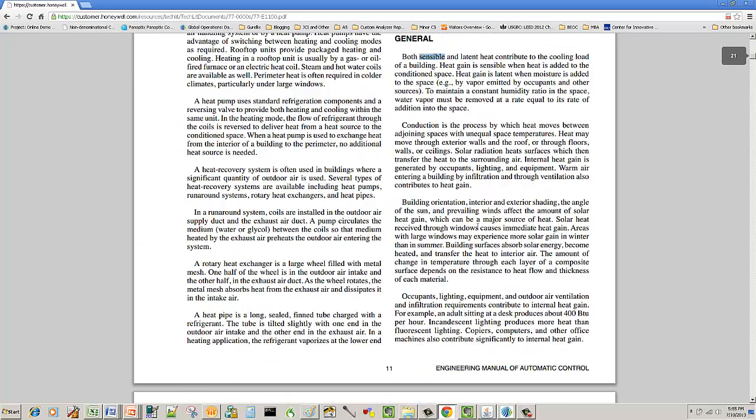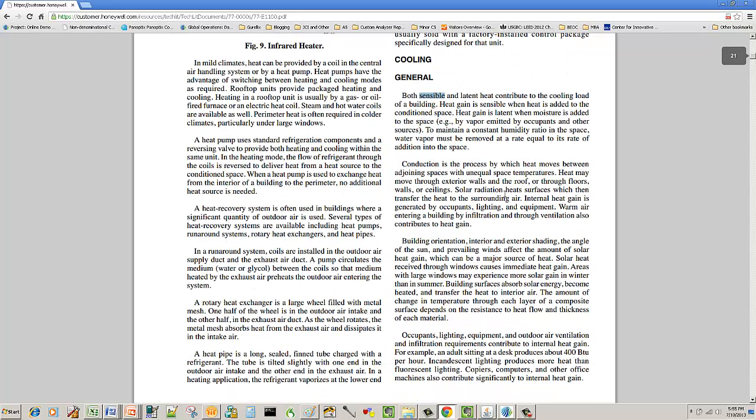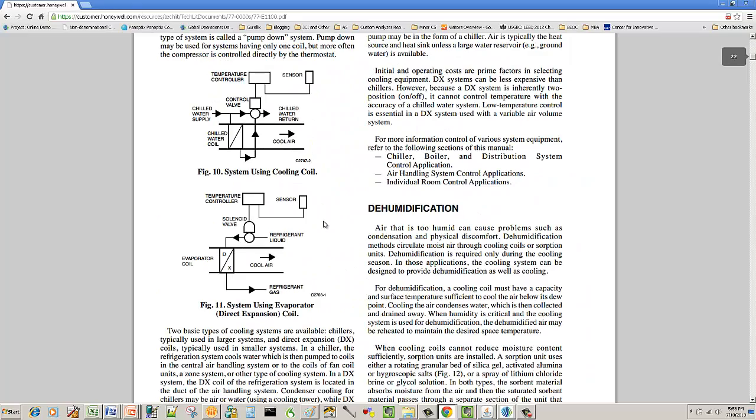Because remember, let's go back here. We can take a lot more BTUs out during a state change than we can during an actual temperature change. I don't have the numbers in front of me, but steam, or gas, is somewhere around hundreds of BTUs. Water is in the single digits, if I remember correctly, and air is, I think, less than 1. Now, I haven't memorized these numbers. Why would I memorize when I have Google and can just go look? But to that point, just know steam is large. And then obviously you have phases above steam. But the point is we're taking advantage of that latent change.